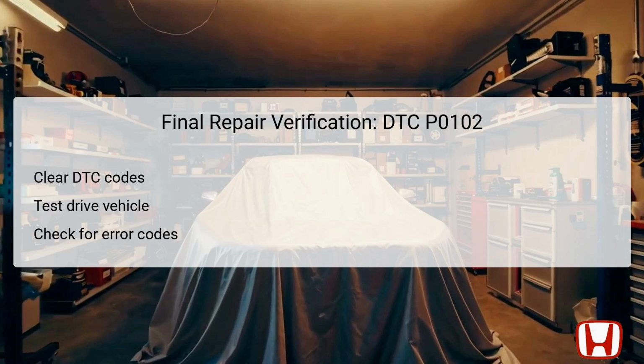After completing all necessary repairs for DTC P0102, it is important to verify that the issue has been resolved. Start by clearing any diagnostic trouble codes stored in the vehicle's PCM to reset the system. Following this, perform a test drive under various conditions to allow the PCM to reevaluate the engine's performance.